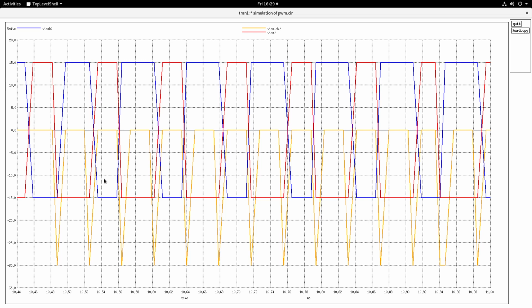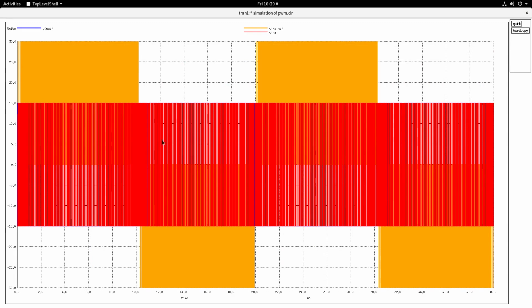The angle, rise time, fall time, is because of the print steps. So it is calculating at much higher resolution, but it is printing at a lower resolution of 10 microseconds. Okay, then coming back here, the yellow portion is the PWM signal, which you are seeing across the full bridge center arm, center portion.